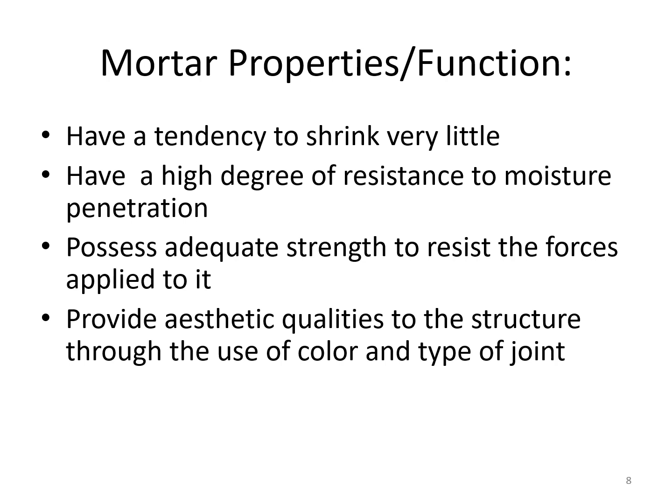Movement in the building itself. Remember, buildings actually move in high winds. They just simply bend and twist, and bricks have to follow along with all this, not to a great amount, but enough that it's significant. And the last thing is to give aesthetic qualities, and that is what brick really excels at. People enjoy it just for the look, and there's nothing like a stone-faced building or a brick-faced building to give a good look and a good solid feeling to a building aesthetically too.